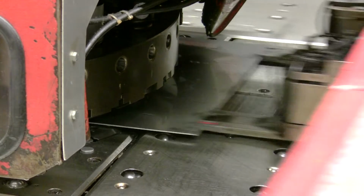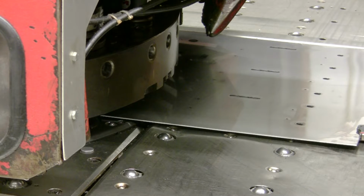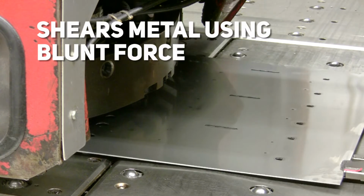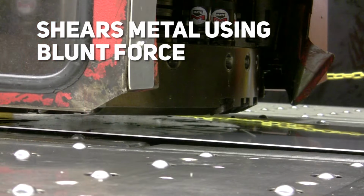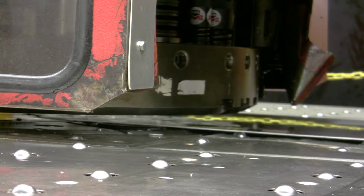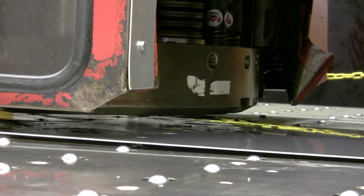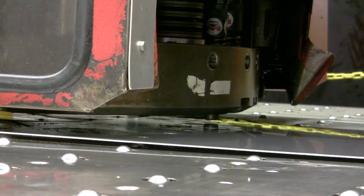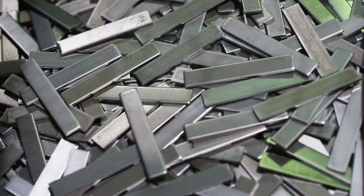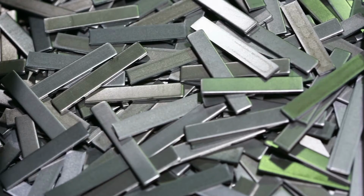Punching uses hydraulic, pneumatic, or electrical power to press a shape, where a punch is forced through metal, consequently shearing the metal. During the process, the punch often passes through the metal into a die, creating a scrap slug. Depending on the material being punched, this slug may be recycled and reused or discarded. When a specially shaped punch is used to create multiple usable parts from a sheet of material, the process is known as blanking.